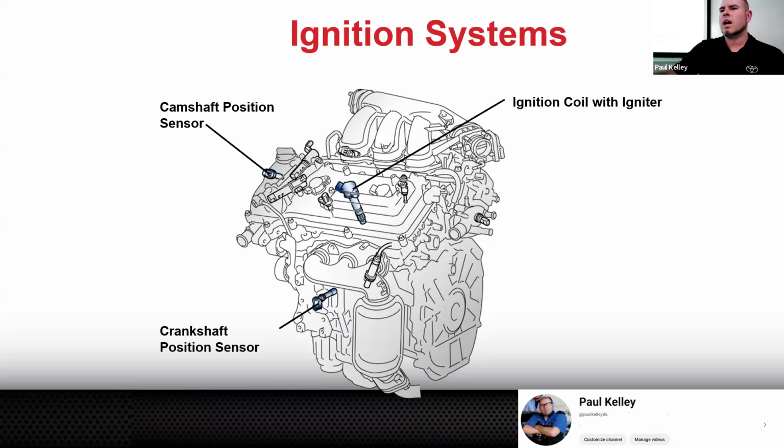I'm not exactly sure what really happened, but I said, okay, so now what's your plan? She said, well, it's got a code set, and my other friend checked it, and we've got this DTC. I have the code in my phone, but it was basically ignition coil 3 primary circuit. And I'm like, oh, all right, that makes a lot of sense. And you said that coil's new? And she said, yeah. And we also changed the coil from 3 to 5, and the code stayed on 3. So think of what I just said. If you move the coil from 3 to 5 and the coil was bad, wouldn't the code follow to cylinder 5, but it's staying on 3? Something with that cylinder. Exactly, right?